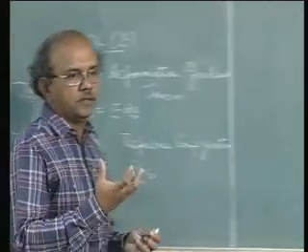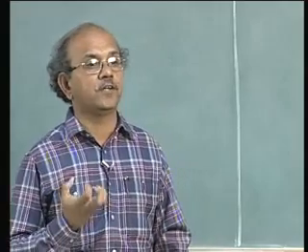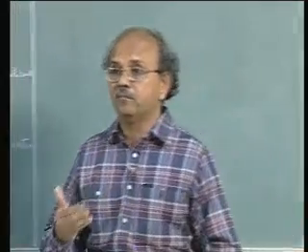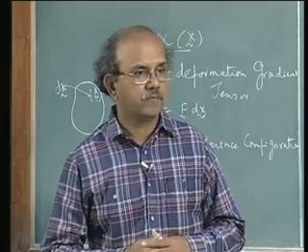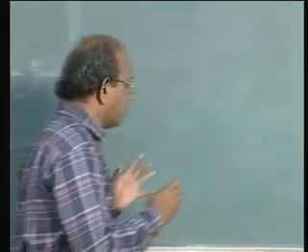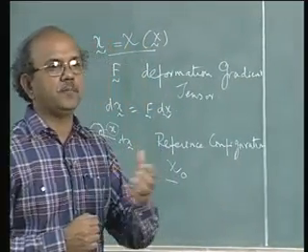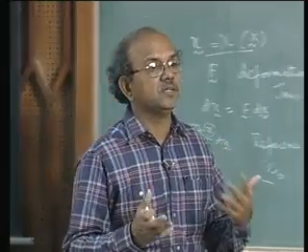For example, if you are doing an analysis of a human heart, what is the reference configuration for this? In other words, what is the stress-free configuration? That is never achieved. In fact, it is very difficult many times, especially in biomechanics, to say what a stress-free configuration is, because that kind of thing will not exist in the time of interest, for example a beating heart, at the time at which it is functioning, it may not even reach this reference configuration.